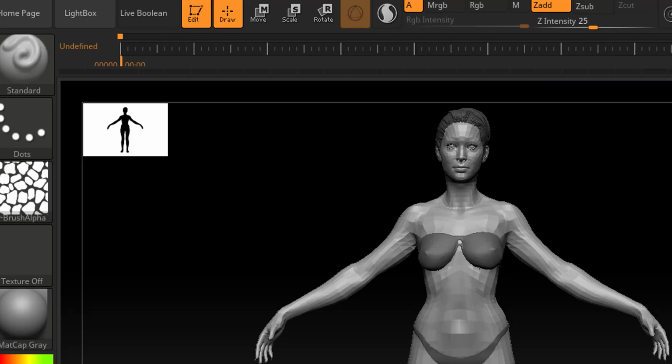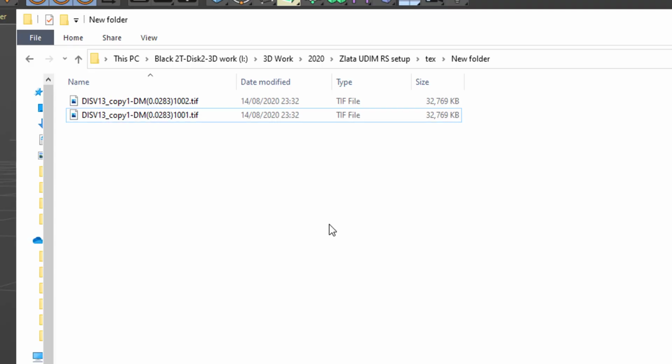If you didn't have the option turned on inside ZBrush with the 16-bit scale, what would happen is that each file wouldn't only not work very well, but it would have a slightly different number put in the intensity level inside here, which means it's actually changed the name convention so they no longer match. So if you find that you're applying everything and for some reason your UDIMs are not working inside Redshift, just check the name convention, because it may have a different intensity level put inside each of the generated textures, and they should all be identical. With that done, we can now move on to the next stage to actually apply these inside Redshift.